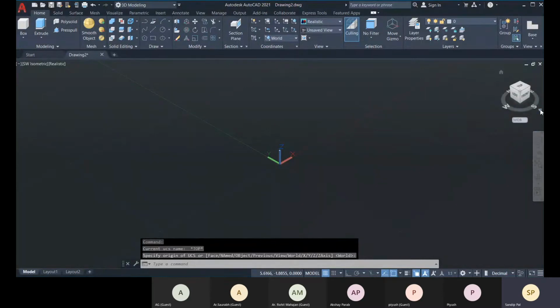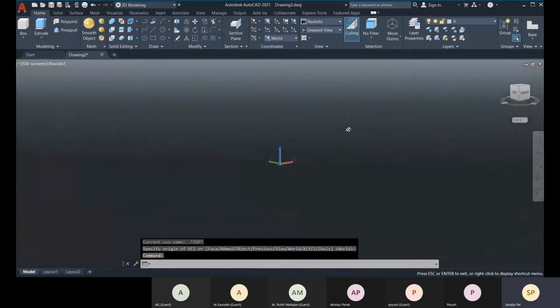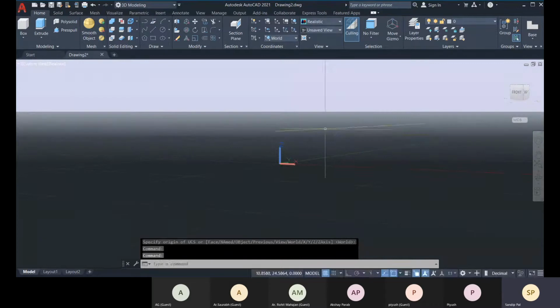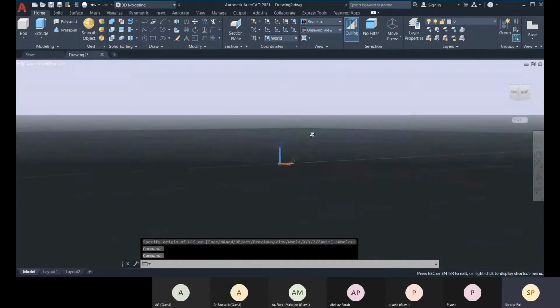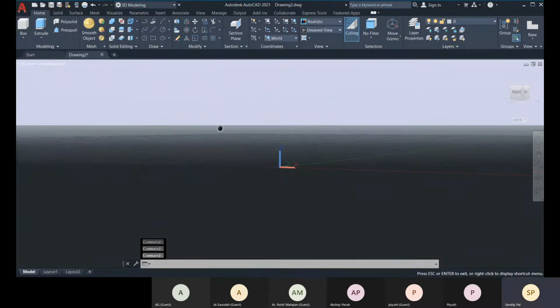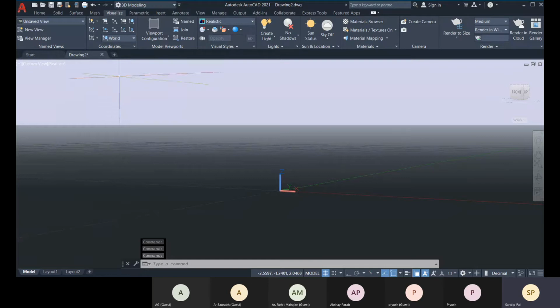this should be WCS, and then your projection is perspective projection. So when you got this perspective projection, if you come into this space where you see horizon, okay, and about the sky, if you go to the visualize tab, this sky is off, so that's why.